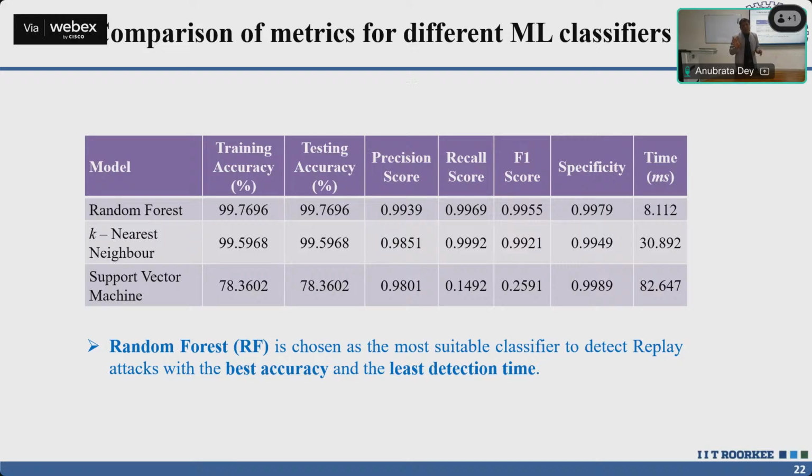And that's why, in power system, nobody is allowing any type of AI or ML based algorithms. Still, in conventional IED, they are using DFT based algorithm. They have not even adopted LES, least error square technique. Why DFT? Because it is standard and proven for several years. The IED which we were using 10, 20 years ago is working without any issue. So that is the biggest problem when you go for deployment, because manufacturers are not ready to accept those things.